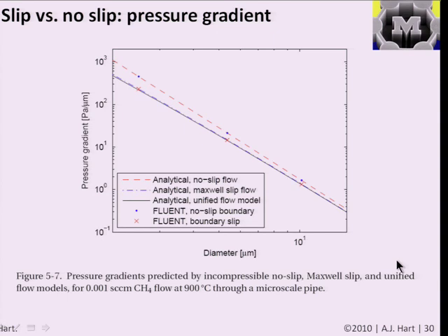And this is just a plot of the equations for pressure drop that we had derived on the previous slides, except I defined S, the slip coefficient, based on what I'm going to talk about now, based on the relationship between the mean free path of the gas and how it interacts with the wall. And that's how we apply the case of the gas to these equations. But it's just having the known value of S and plotting those equations as a function of the geometry.